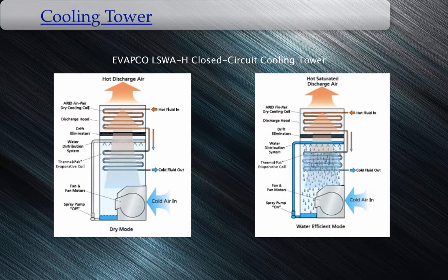Cooling tower. The cooling tower is a forced draft, counterflow, closed-circuit cooling tower with a centrifugal fan. Forced draft. This was used to isolate the fan's moving parts from the saturated discharge air. Counterflow. This was used to maximize the contact between the process air and ambient air.